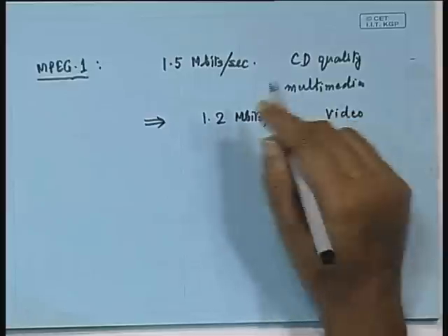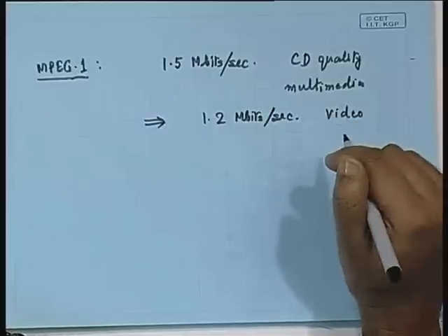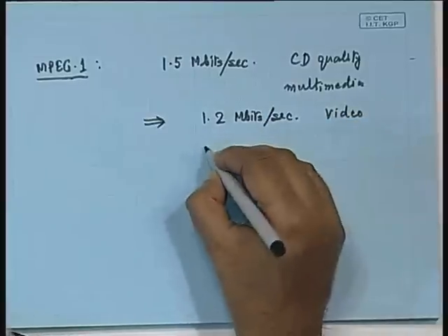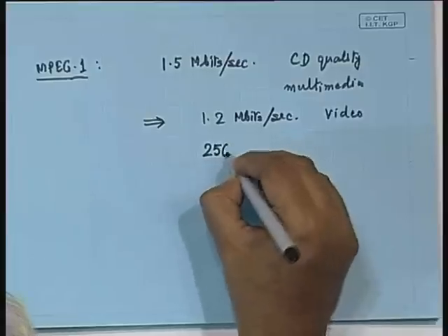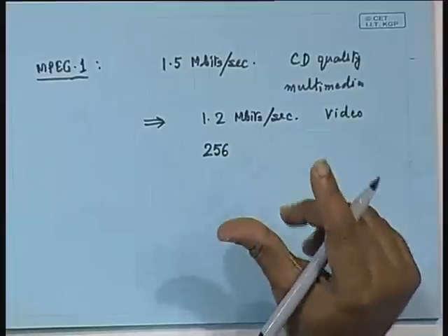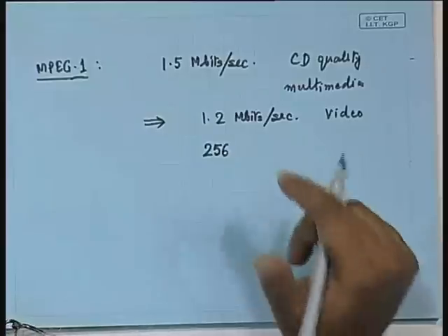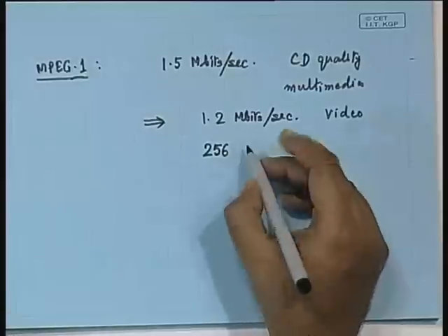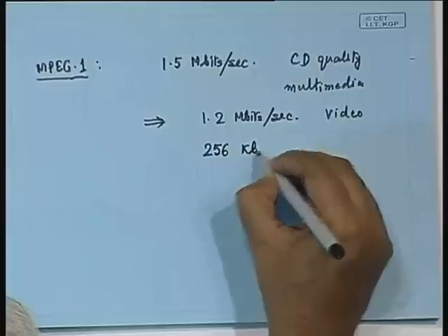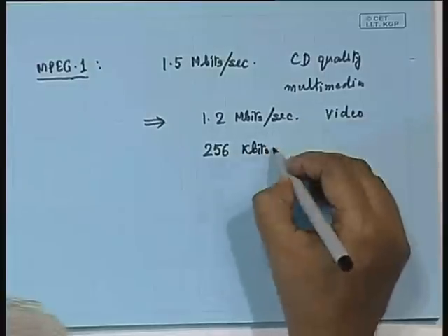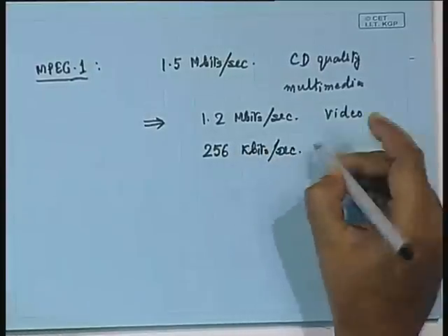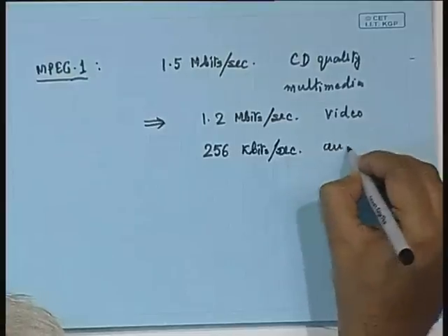and the rest, that means roughly 300 kilobits per second, to be very precise, leaving aside the synchronization bit requirements and the header information that goes into the packet, payload wise we get 256 kilobits per second for the audio.